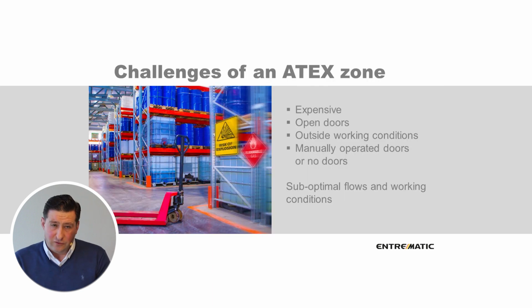Challenges of an ATEX zone. First of all, an ATEX zone is always an expensive thing because as soon as a certain area is classified as ATEX, this means that all the electronic or electrical equipment should be certified ATEX equipment. This is from lighting bulbs or lamps, communication equipment, every electronic component used in such an area has to fulfill the ATEX regulation.